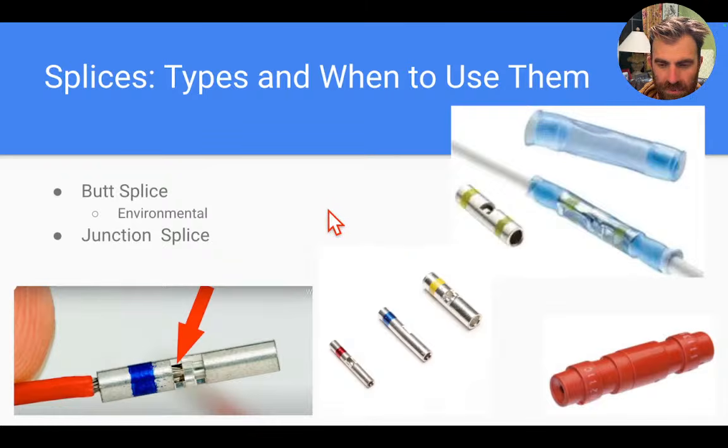And these are mainly used for terminations or for making wire repairs. So if you found a damaged wire and you had to cut it and splice it back together, this would be a way to repair damaged wiring.